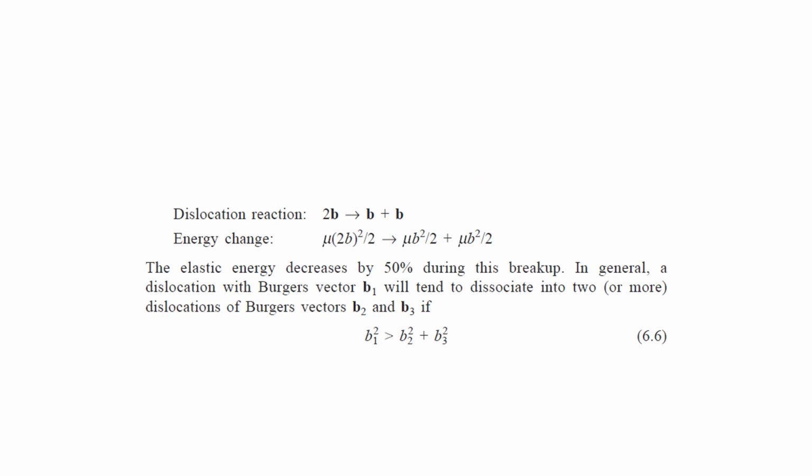In real practice, dislocation in a crystal can be classified either as full dislocation or partial dislocation. For a partial dislocation, the Burger's vector is a fraction of lattice translation. For a full dislocation, the Burger's vector is an integral multiple of the lattice translation. We are mainly dealing with full dislocation here.